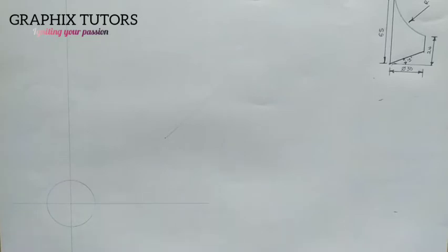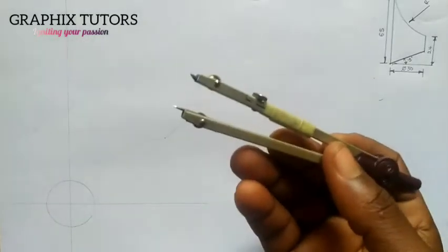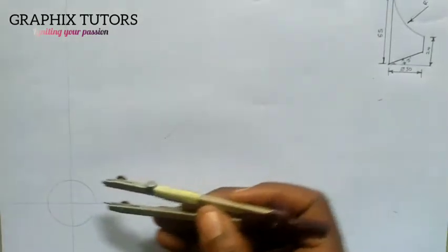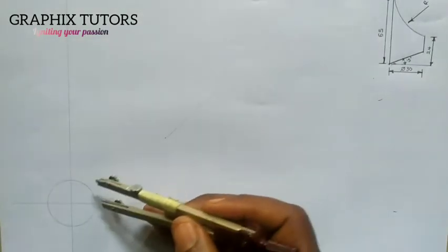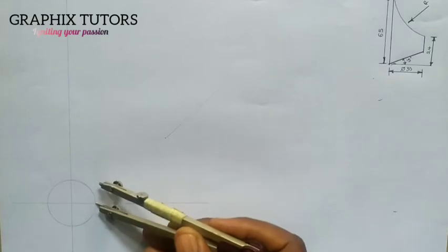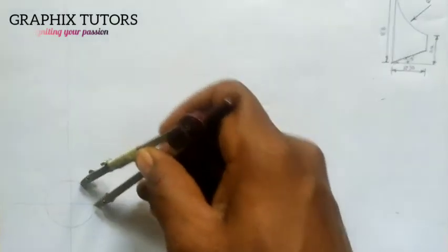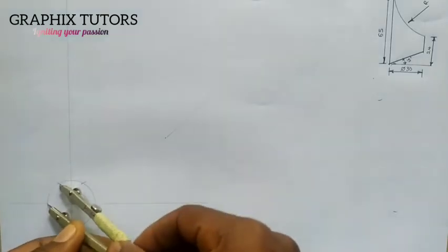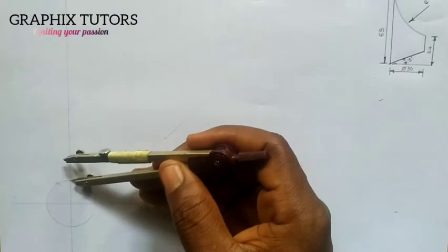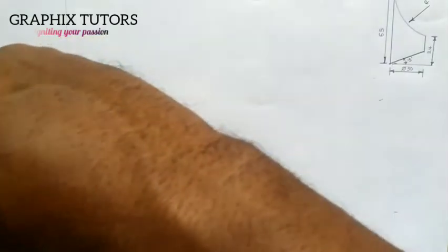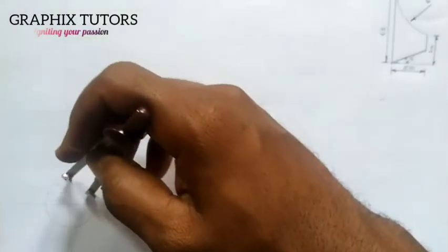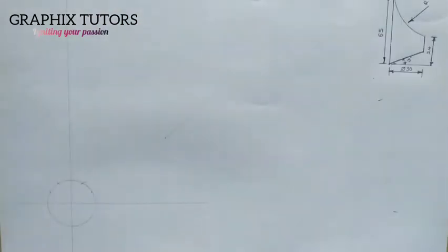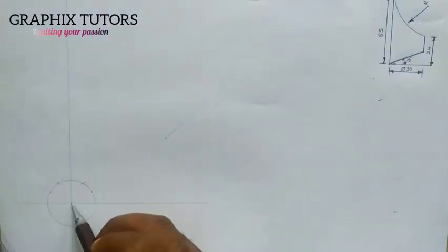Now the next thing is I'm going to divide this circle into 12 equal parts, right? So either I use my set square or I use the same radius I use for my circle. With the same radius, I'll place it at this end here and strike up. I will come to this other end also and strike up. I'll come to the center here and I'll strike left and right. Now with the help of my meter rule, my focus should be at the center.